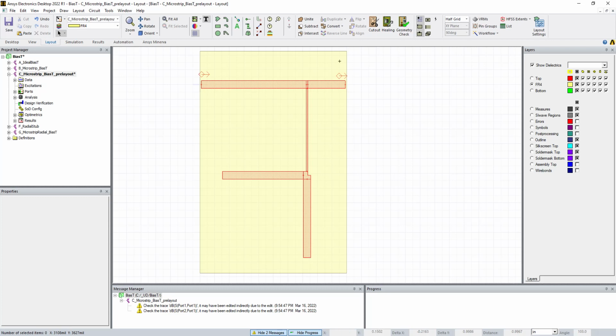Well, the length of this PCB I arbitrarily picked as 1.5 inches. So what I'd want to do, and this starts at 0, 0, is what I really want the length of the printed circuit board to be is this offset, which again was WCO. This is the connector offset, right? That takes us from here to halfway through this trace. And then from there to here is half this trace width. From here to here is P stub 1.